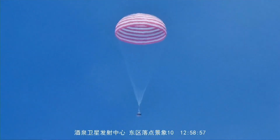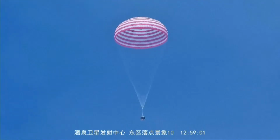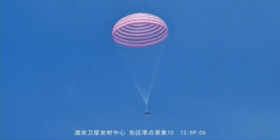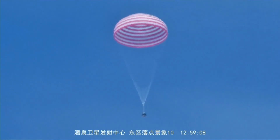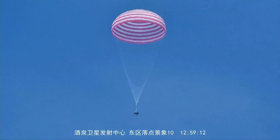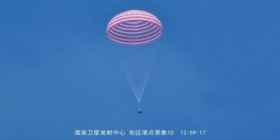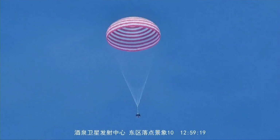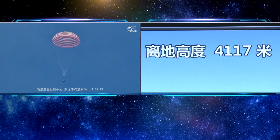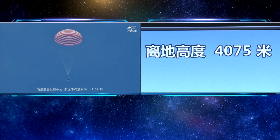You know that just on the bottom of our re-entry capsule, we have one device called a gamma ray altimeter. It will emit gamma rays to the ground, and with the reflection, it has a receiver to measure the time. So we can have a very precise measurement of the distance between the bottom and the ground. So it will send signals to ignite the 4 rocket engines and slow down the vehicle to, as mentioned, less than 2 meters per second. Right, and that's automatic? Yeah, this is completely automatic.